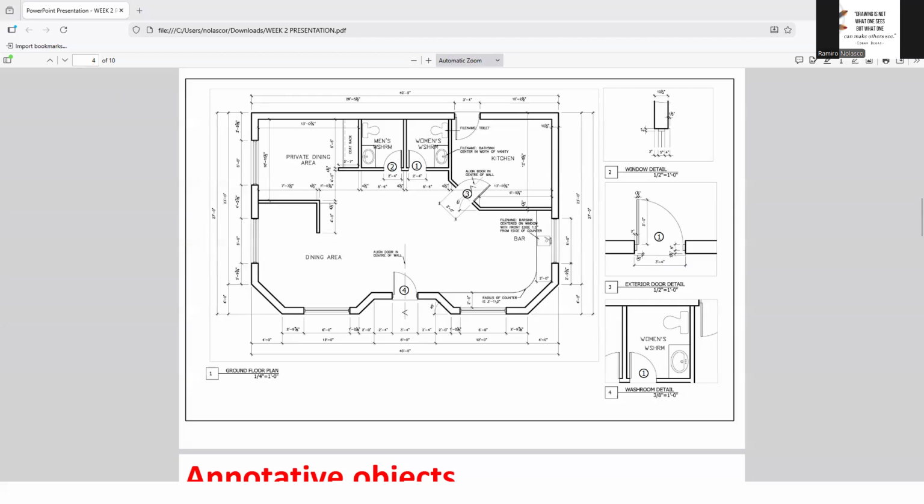And precision. Change that. Okay. 27 feet, 0 inches, right? Yes. Let's see if that will do it. Click OK, close. No, it didn't do it. How do we show that? Modify.